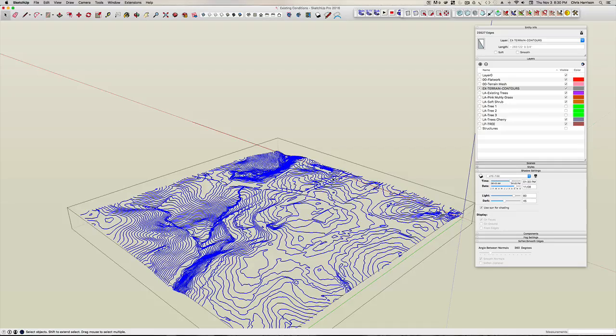So I'm just recreating that terrain mesh again. It might take a little bit. So we have a clean base, and I'll paint it green and leave the structures embedded, and have the contours on the outline as a reference for the site. Then we'll update the CAD, drop it in, and then we'll make faces, and this will be the final model. In the meantime, I recommend somebody grabbing these buildings and fixing them, at least the hero buildings, the ones on the site that we're focusing on, and model them how you think they should look. Maybe not so much the interior, but certainly the exterior facades.